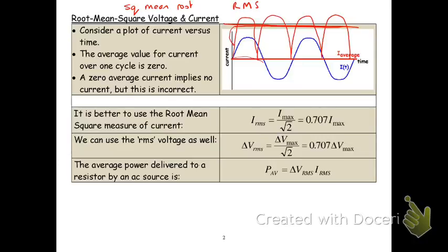Because here's the issue. If I have a voltage versus time relationship and a current versus time relationship, and I use P is equal to I delta V. Remember what we said for power? This is power, joules per second. If I take the maximum voltage and the maximum current, it's only at those two values for an instant every cycle.